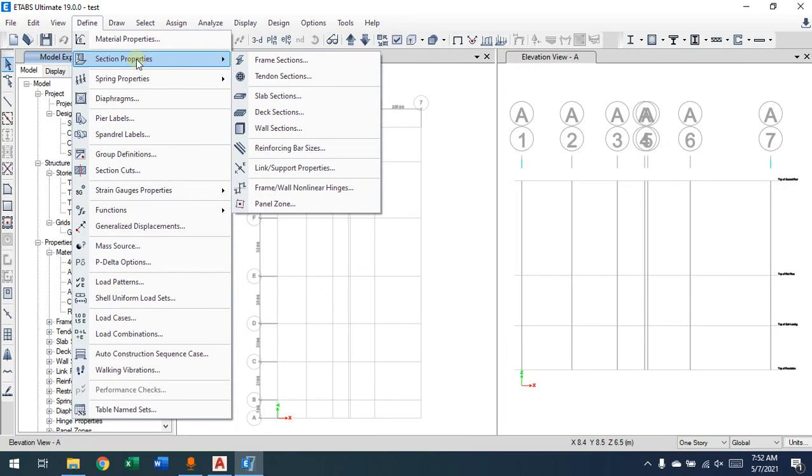So the program works in the same way. You still have to go through preliminary design. The first stage of design of a building is preliminary design. You do a quick analysis, which most of the time will be approximate analysis, at least to get an idea of the approximate loading on the building, and according to that loading you will come up with some sections, then bring them into Etabs or any other software in order to do appropriate analysis and design.